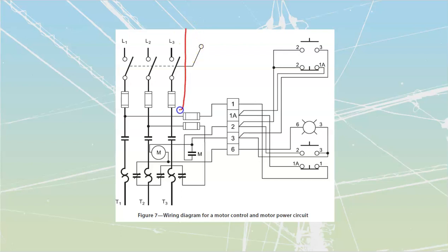First of all, we're going to start this drawing over here by defining what we have inside of the different parts. The book doesn't really show it over there, but you should recognize that these are the components you will find inside of your disconnect switch. So it's going to be my fusible disconnect. I've got my switches. I have also got my fuses, which are there to provide the overcurrent protection. Not overload, but the actual overcurrent.